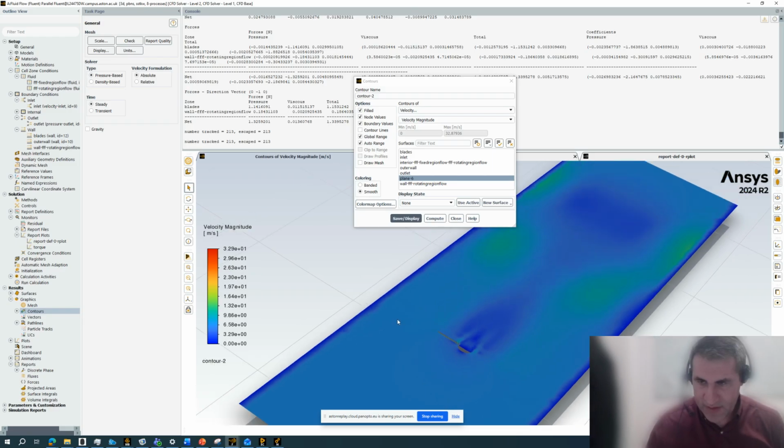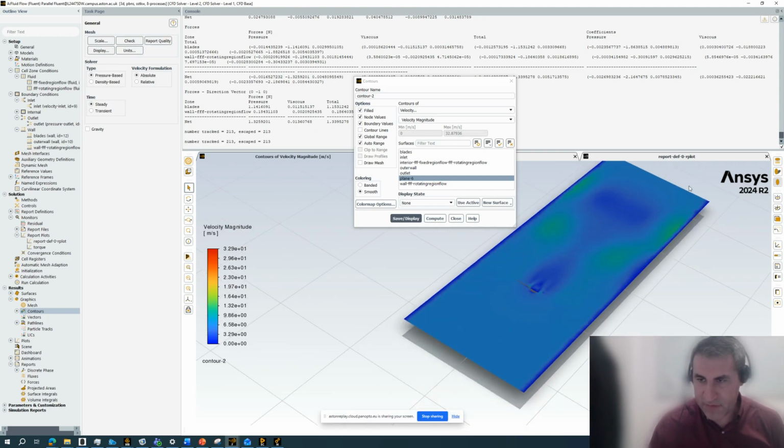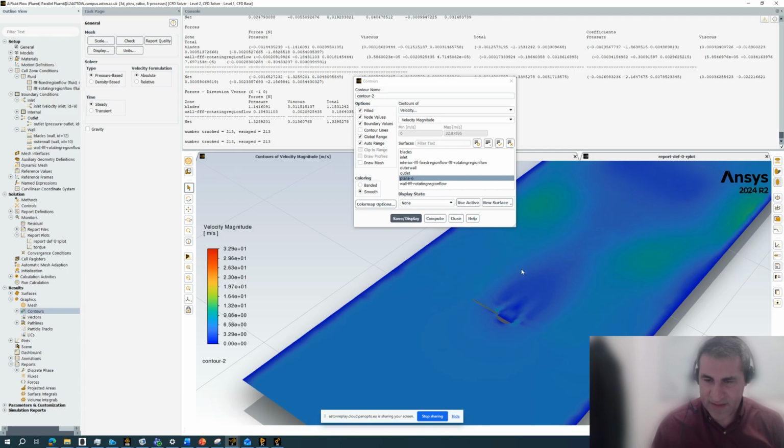There's a velocity, and the effect of the wind turbine extends to this point. Perhaps if I have the backside further away, I could have seen more variation here, but because I set this outflow here, that may not be realistic. This might want to be very far back in the realistic problem. So that's why I prefer to have the back as far as possible, because behind the wind turbine, lots of things are happening, and that's a wake behind the wind turbine.